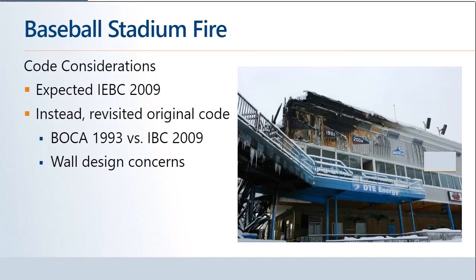So we had to look back at BOCA 93, which was their original design, and then start looking at the new codes as well. And why we had to do that goes back to what Brian focused on a couple of times, where he says, was it lawfully in existence? Well, if the walls weren't built or reinforced to the code at the time that they were constructed, then they weren't lawfully in existence. So even though they were providing decent service and hadn't failed, they weren't right from the get-go.